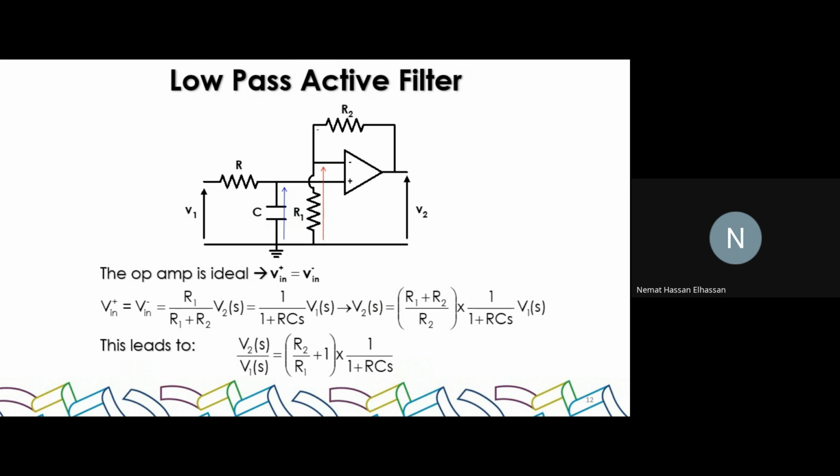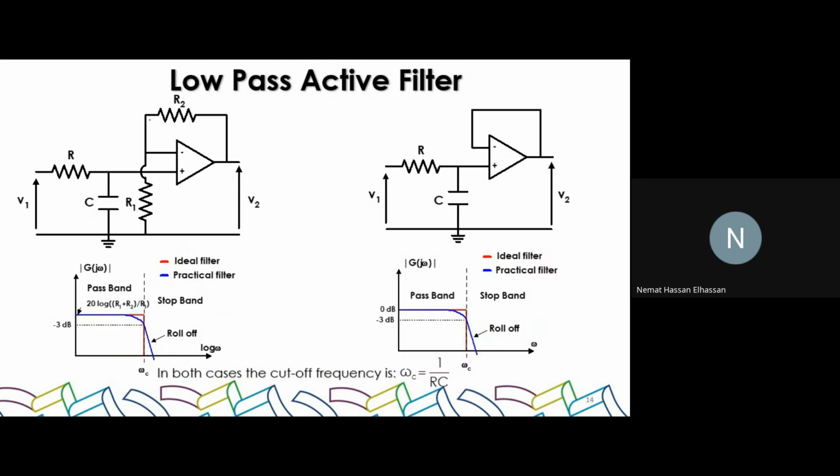Now we've already been through this process. If you compare the gain, this is the gain without amplification. You'll notice it looks like a passive gain. And with amplification, this line, you'll notice now it has an amplitude. So if you plot them line by line, this is without amplification. It will go like this. It will be a slightly lower gain. With amplification, it will be a higher gain. The cutoff frequency will remain the same. So the amplifier ideally doesn't change the cutoff frequency. The passive components are the part that do the filtration. The op-amp only enhances or boosts the voltage value. Are we clear so far?